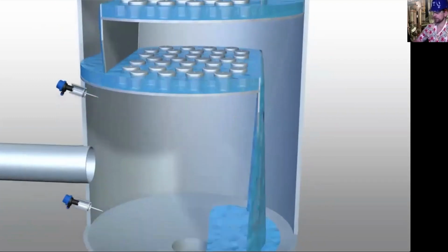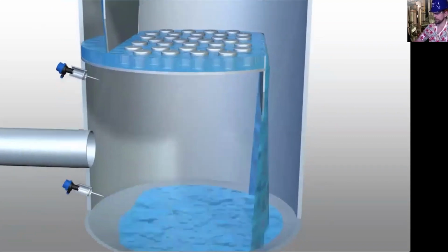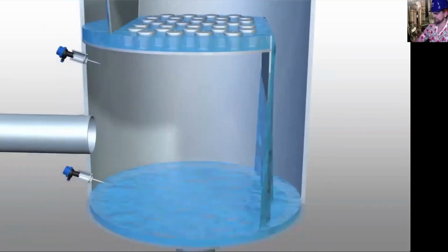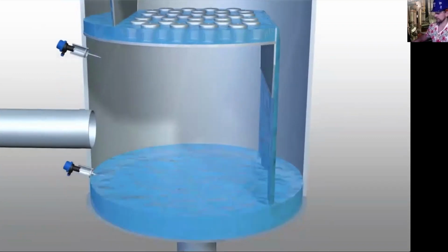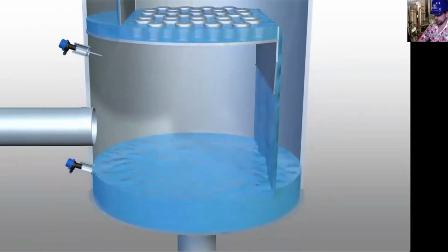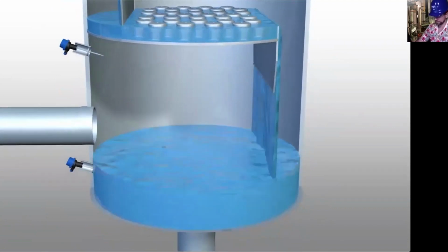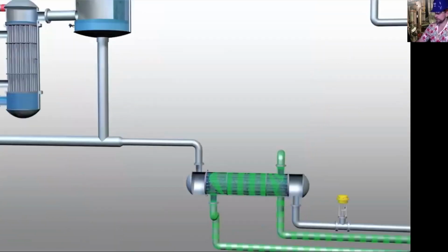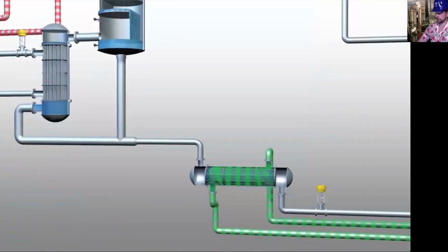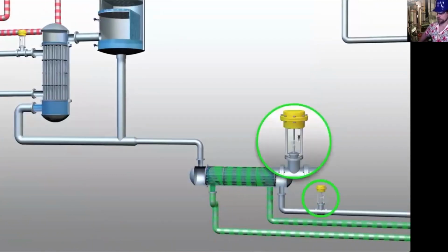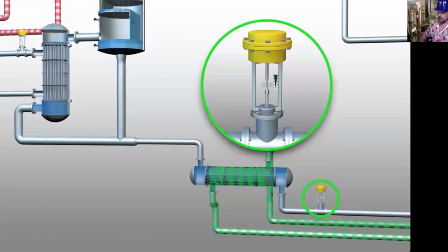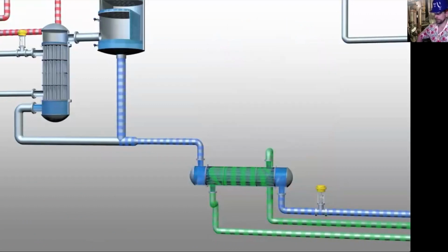Now, as I mentioned, we are in the process of starting up our column right now. So there are a few specific things that you'll want to do whenever you do this. The first of those would be to open that flow control valve at the bottom, so you don't have a buildup of liquid in your column, because that could cause hydraulic pressure to build up as things overfill and vapor can't get through. It could lead to an explosion.